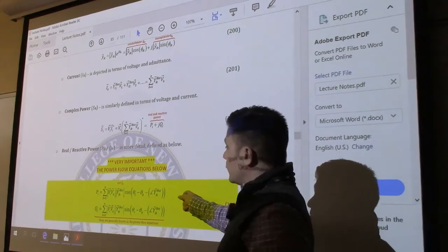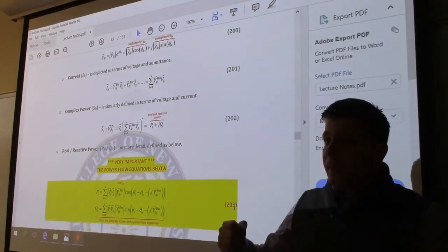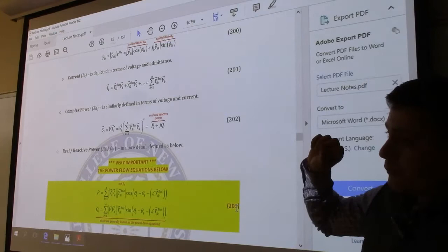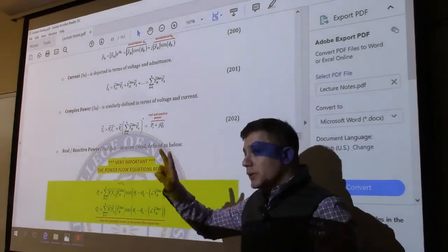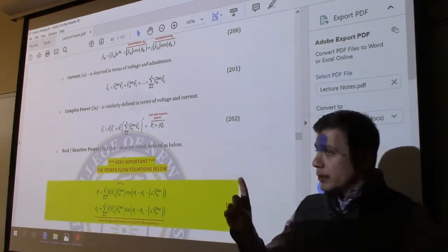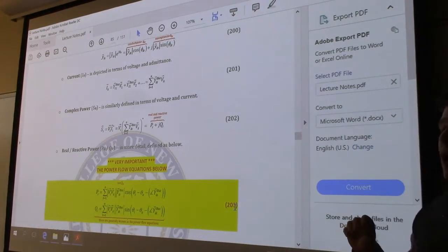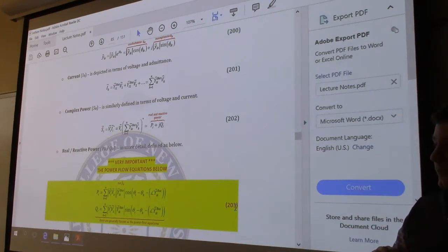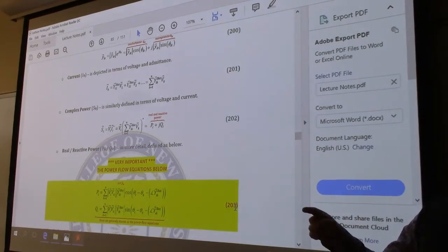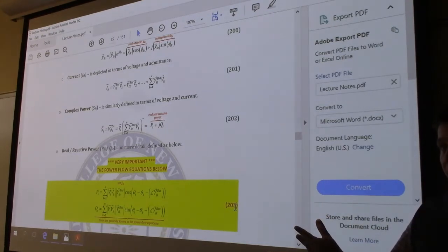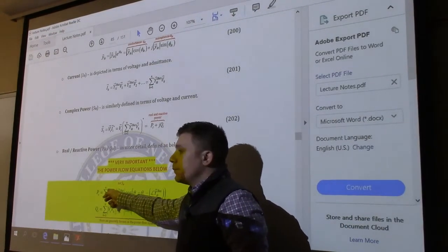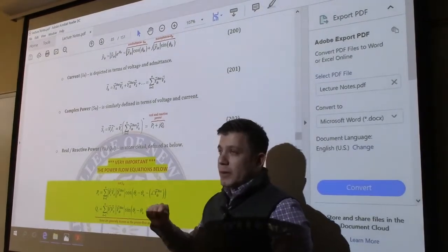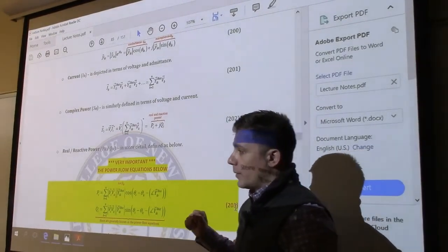And so, applying these, if we have 3 buses in a system, we're going to have to use 2 different sets of these equations. The reason why we only need 2 is because we don't have to solve for the infinite bus. So we're always going to be solving for 1 less bus than we have. So if bus number 1 is the infinite bus, then we'll be setting up these equations P2, Q2, P3, Q3. We don't have to worry about P1, Q1. Okay?